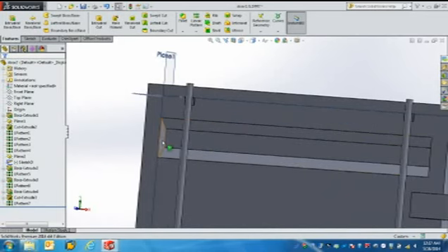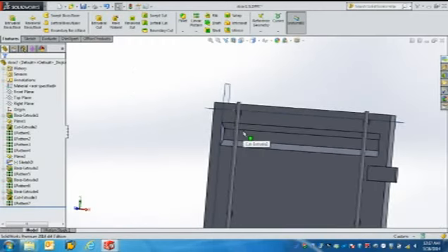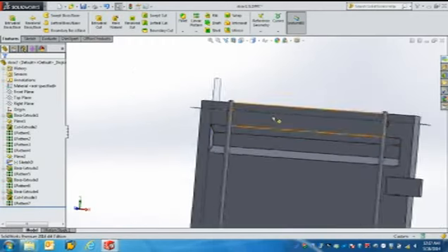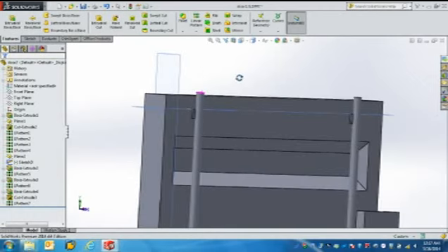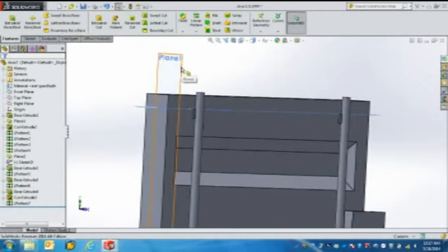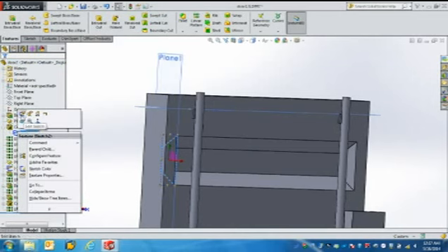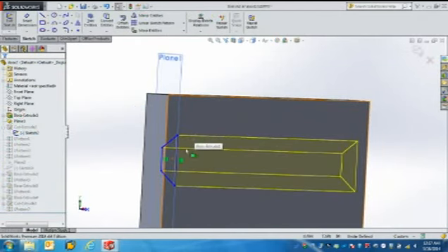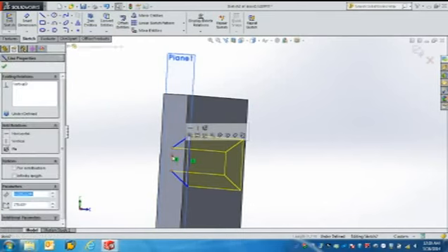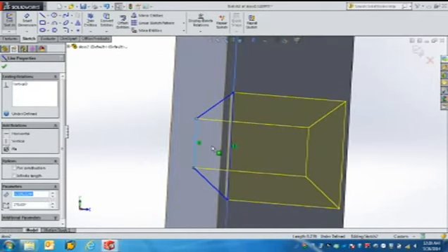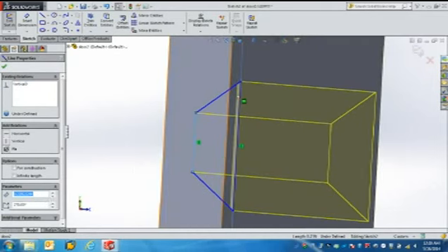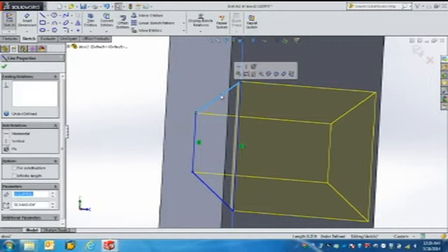Well, I have chosen this plane and then I have sketched the cross section of this slot, that is this one. Well, the dimension of this floor line is 0.22 feet. This one is at an angle of 38 degrees and with the length of 0.21 feet. Similar thing goes here, and we will complete it by drawing a line here, and we will have a closed geometry.